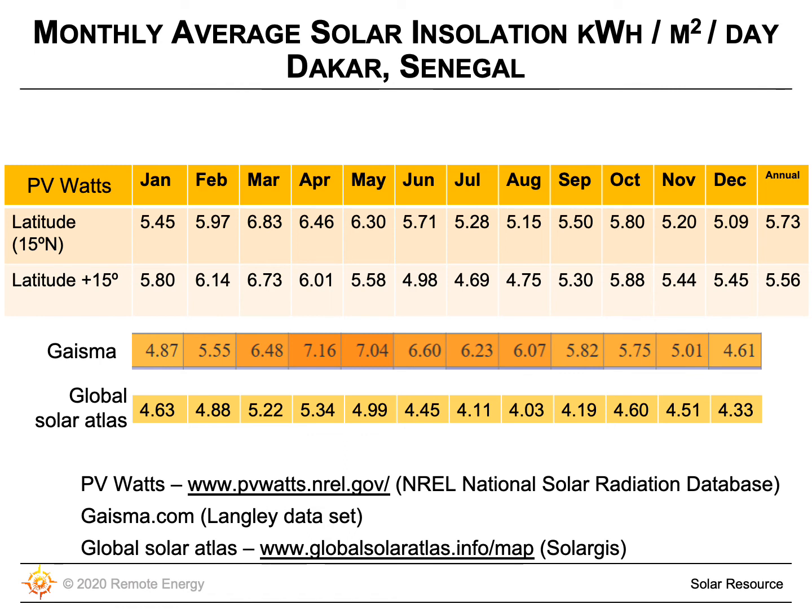So two very different values there for the same month at the same location. Again, the values are different because we're using a different angle to collect that solar insolation. Looking on in that same data set, if we move to the months of June and July, you can see that the collector that was angled at the latitude angle of 15 degrees is actually receiving much higher insolation values in the months of June and July than the one that's tilted farther up.